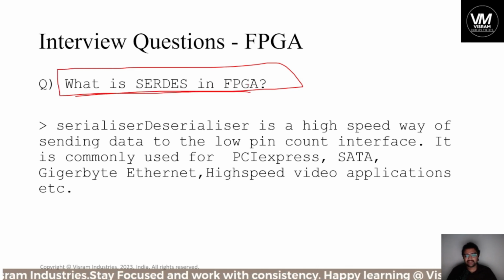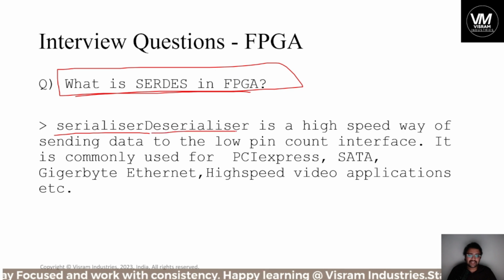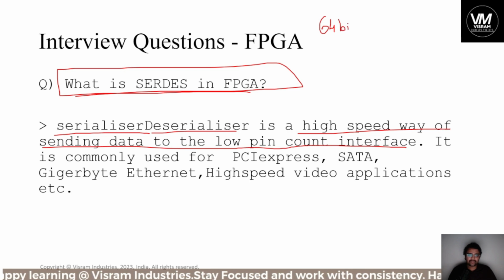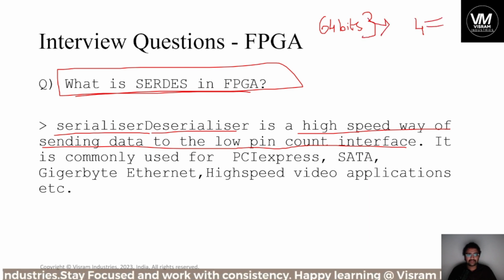This can be asked if you are applying with some experience. SerDes is nothing but serializer deserializer. It is a high speed way of sending data over a low pin count interface. For example, you have 64 bits of data, and that 64 bits of data should be sent through only 4 pins.